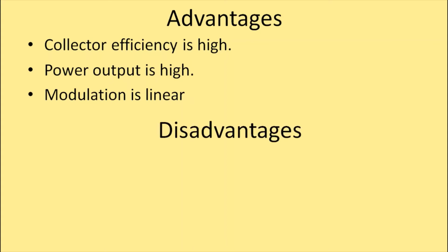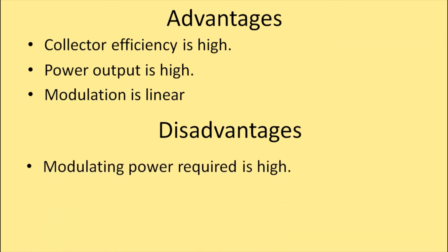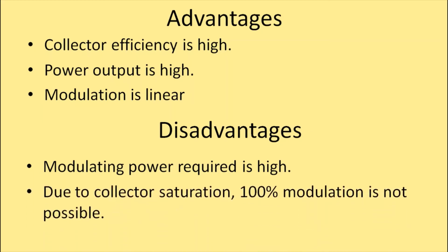Coming to the disadvantages, the first main disadvantage is the modulating power required is very high, and the other disadvantage is, due to the collector saturation, 100% modulation is not always possible or not possible at all.